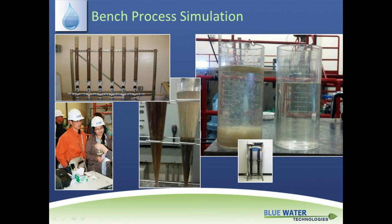For example, this picture here is a coal FGD plant application, where we were interested in removing mercury, selenium, arsenic, and a couple of other trace elements as well. And you can see this is one water sample. It's just been split into two jars. You can see that in removing or targeting those elements, we can, in many applications, also get a fair amount of precipitation of other dissolved solids. And so that has to be managed through the project and through the process design as well.